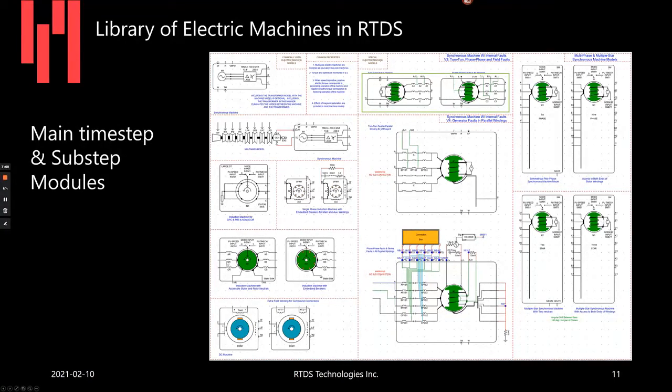You have another three-phase induction machine, with which you can dynamically change the MVA and also have embedded breakers. Also, you have access to both ends of the windings if you want to change the delta or Y connection of the winding on the fly.